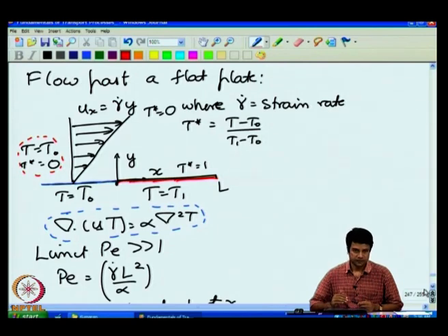So, you would expect the flow to sweep any heat that is transported from the surface downstream, and physically one might expect the effect of the plate to be restricted to a thin layer near the surface. Diffusion is present nevertheless, and therefore, one cannot have a discontinuity in the temperature, but that diffusion effect is small compared to convection over length scales comparable to the length L. And because of this, we would expect the heating due to the plate to be restricted to a thin layer near the surface.